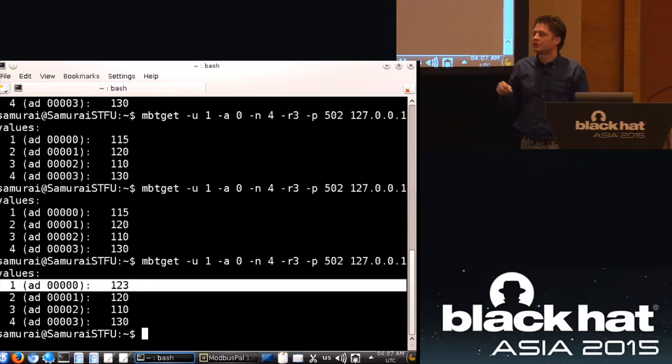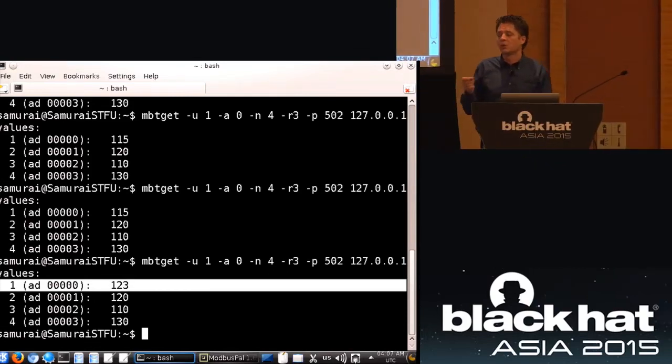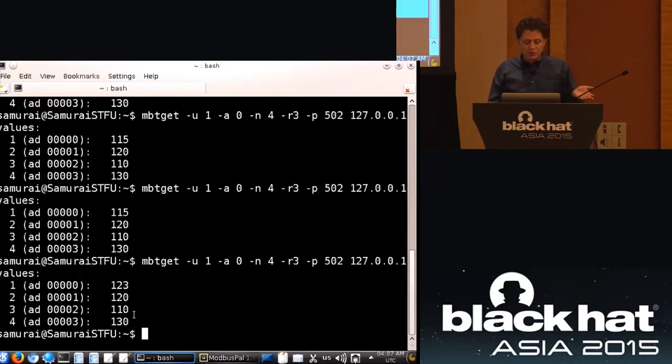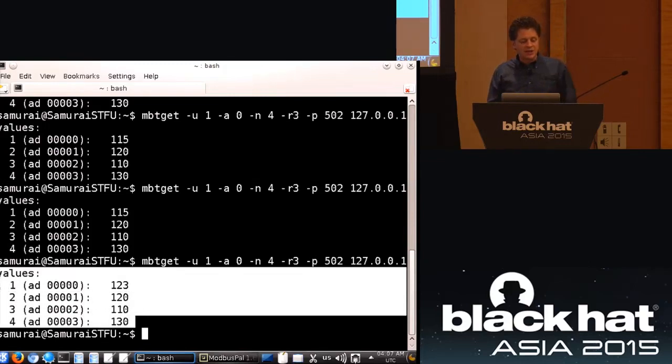And it will go through and do it. Now, in a normal control network, you're going to have a master server that is constantly polling that device and making those readings. Most of the time, they'll make those every 2 seconds. Could be greater or less than that, but 2 seconds is a very common polling interval. Okay? So this allows us to identify these different types of values.